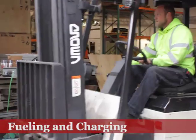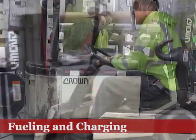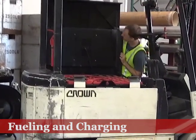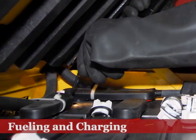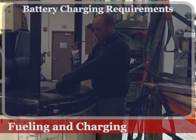While electric forklifts have zero emissions, and eliminate carbon monoxide exposure, vehicle batteries can be hazardous. Battery charging can produce flammable hydrogen gas, and battery acid can be very dangerous. Employees performing battery maintenance will require specialized training. Here are some additional safety rules for battery charging and maintenance.